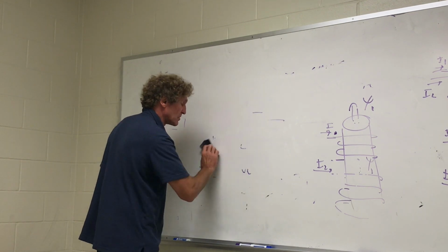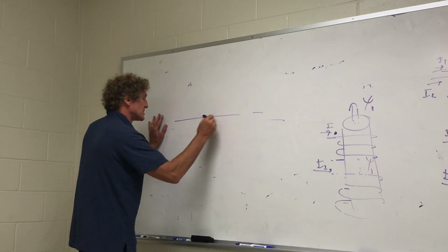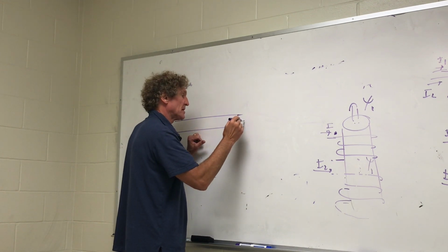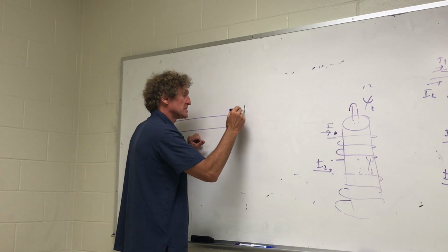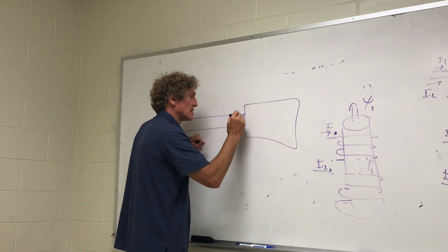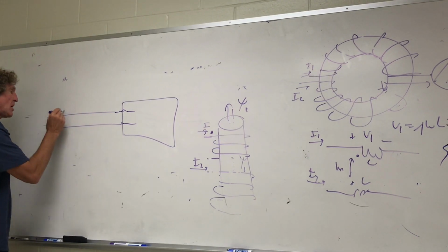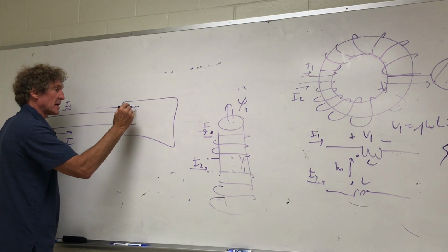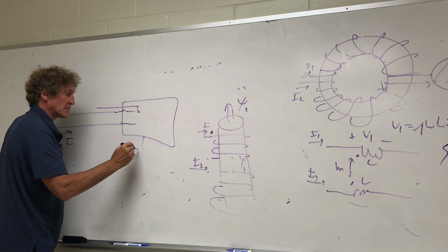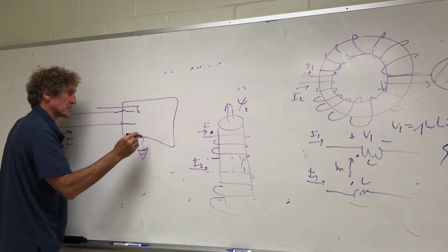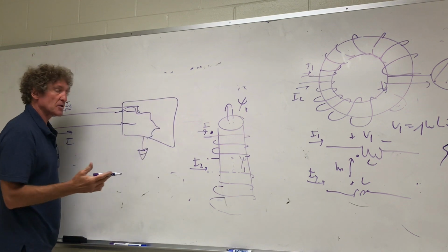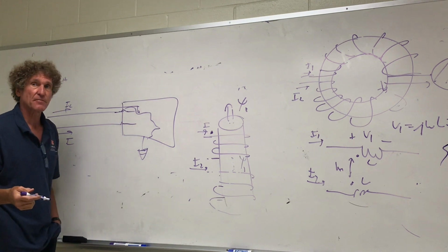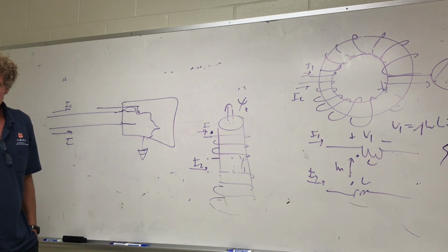So here's why it's so important. Let's assume I have long wires here, and they're going in and feeding some devices. Here's my chassis. Wire comes in here, in here. If you have common mode current, especially really large currents, this current goes in there, it's trying to get to the earth ground or chassis, and it's going to go through your circuit whatever way it can find, path of least resistance, usually through things like differential amplifier inputs, and destroy them.